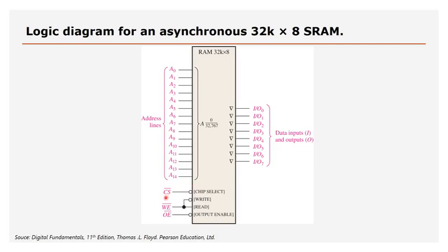And if the chip select is not 0, irrespective of what happens on the address bus or the data bus or whatever happens with these two pins here on the control bus, if the chip select is a 1, this device is deactivated. But if it's a 0, this device becomes active. Now we've got these two pins here, which is the WE, which stands for write enable, and the next one here, which is the output enable.